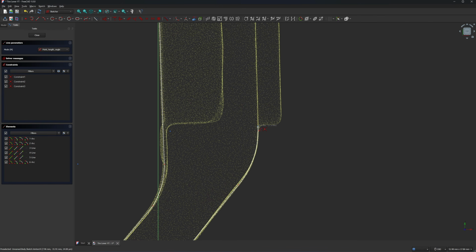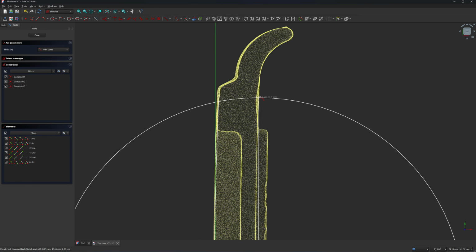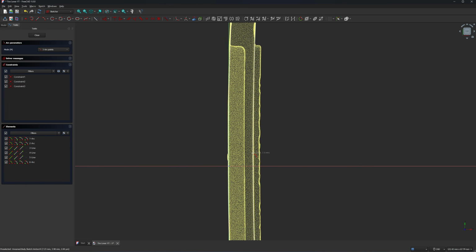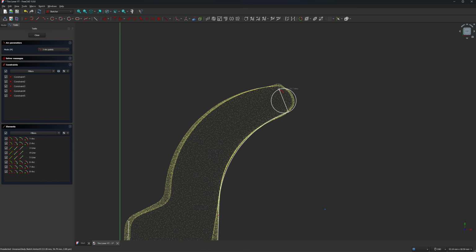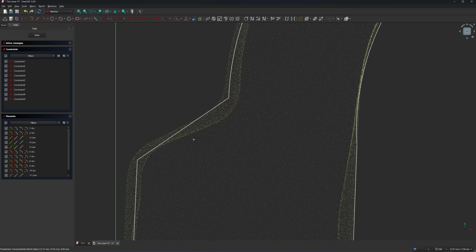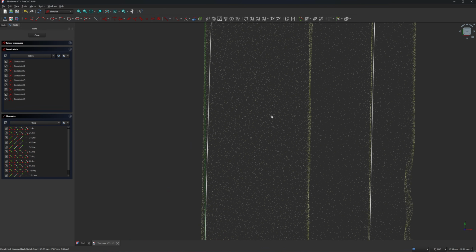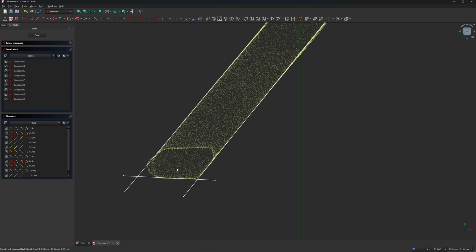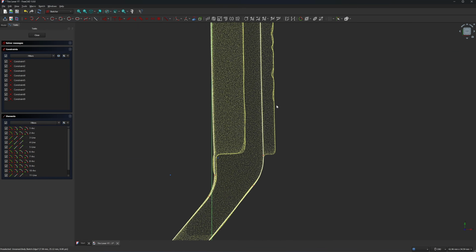You can lock the line, put a tangent constraint. I'm not going to do that. So this one bends a little bit more. Put some arc here, another arc. Okay, now make sure that the line is all connected. Look at the color of the point. It has to be red color, so that this means it's joined properly. Okay, everything is joined.